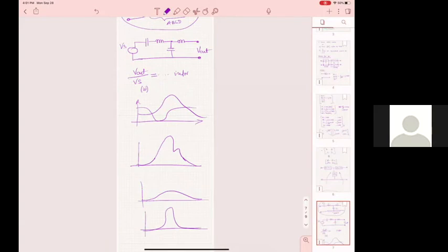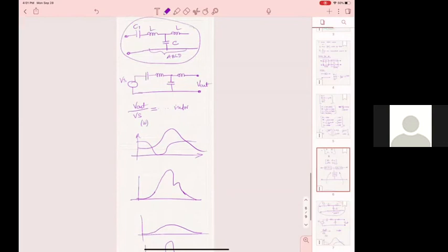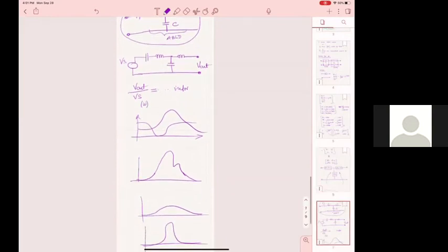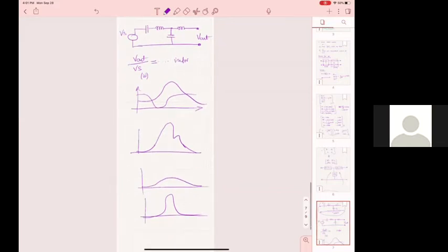For the purpose of classifying this behavior, you would say it's a bandpass because we know that the low frequencies and high frequencies are down, right? But you don't know exactly how it looks. It may be a very poor one, all right?